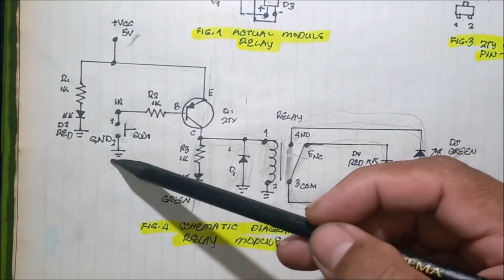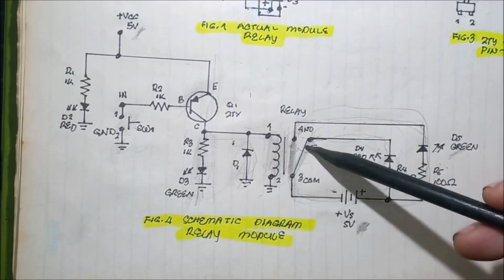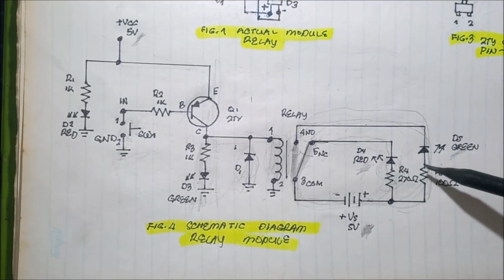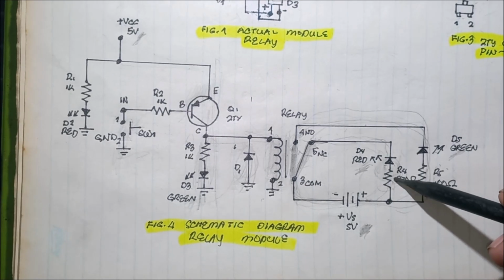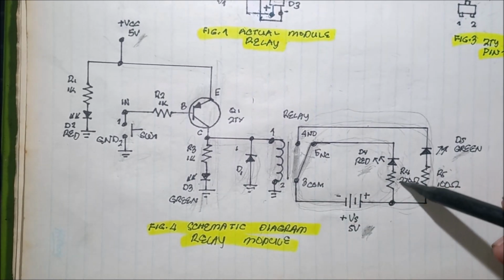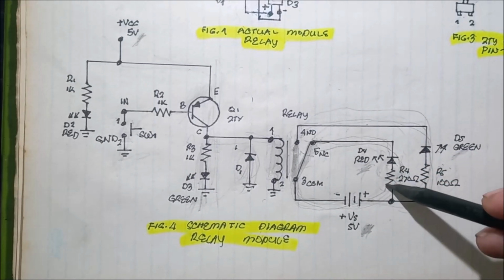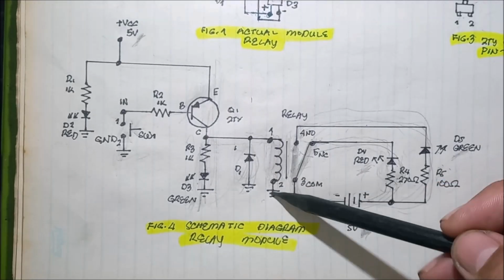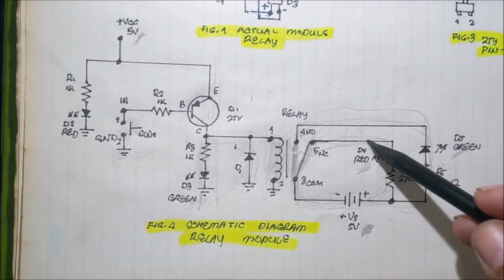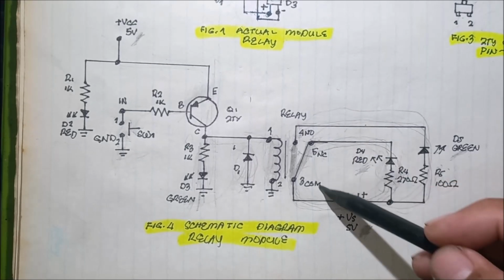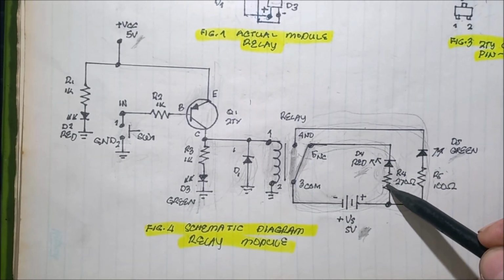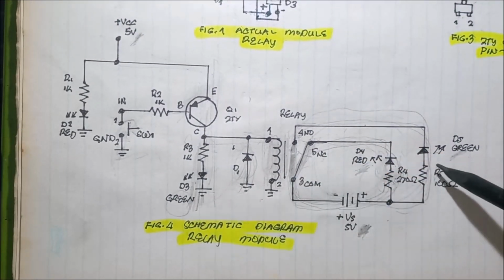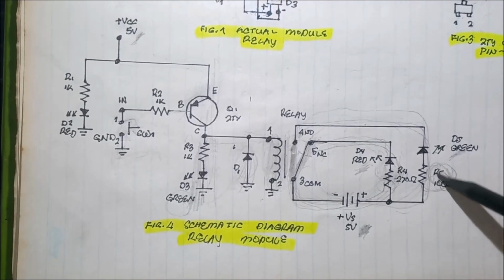Once we release the switch, the contact goes back to pin number 5. So the green LED now turns off and the red LED turns on again, because there is now a complete circuit to the red LED, since the switch is open and the relay is deactivated. If we press it again, the green LED turns on, also the green LED on the output side or the high side.